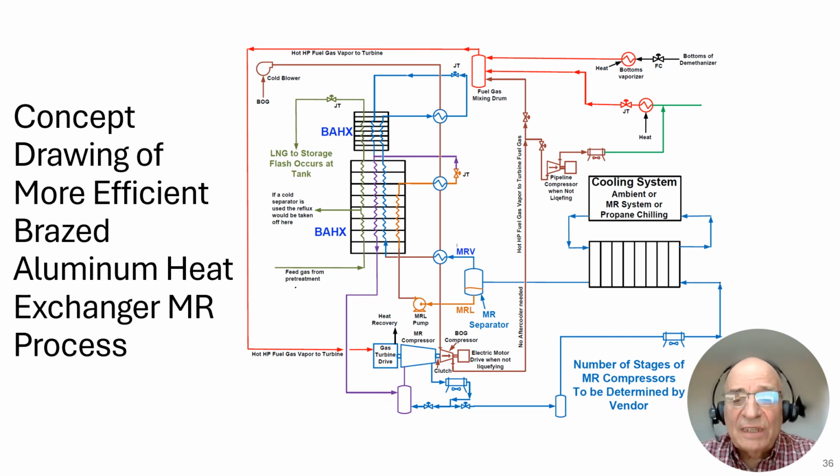Let's take a look at the MRV. That's MR vapor. Well, that consists of the more volatile components in higher percentages. That's nitrogen and methane, more nitrogen and methane than ethane and propane. And that MRV comes into this heat exchanger. It is cooled down by the MRL that has been flashed, that has been pressure dropped across the JT valve. It is cooled down by that MRL that is being boiled off here, and it keeps on cooling, and it goes into this next heat exchanger where it cools down even further and becomes a subcooled liquid.